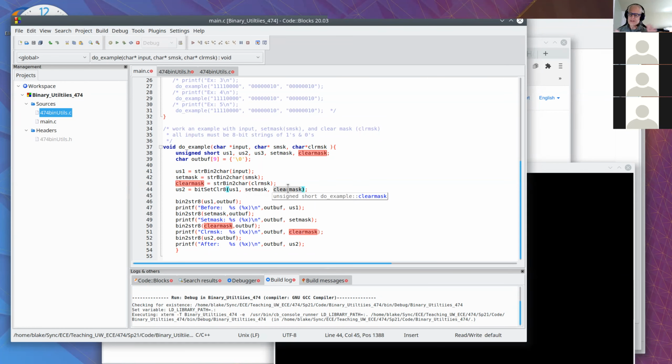And I showed you two ways to represent that. What we're talking about here is if we want to clear a bit, we have to have a 1 in that position, which is sort of counterintuitive, but it's also intuitive because you could say where we intend to do something, we put a 1. Where we intend to leave everything alone, we put a 0.